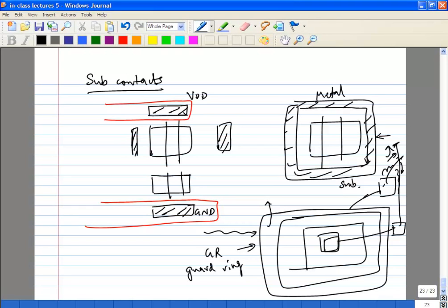There are obviously cases where you may not have so many pads, in which case you would have to decide. Depending on whether the circuit is noisy or whether you're interested in protecting it, you'll have to decide to group the grounds together. That is a totally different topic by itself. That is something you definitely will have to make a choice on. If it is a very sensitive circuit, most people would prefer to connect its own substrate to its own ground, rather than connect it to the guard ring, especially if there's a noisy circuit.